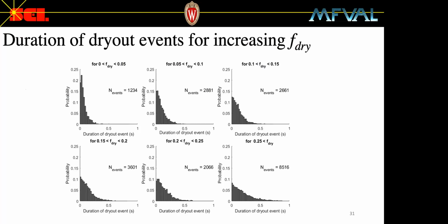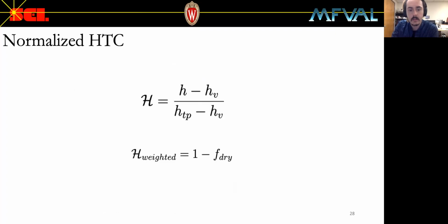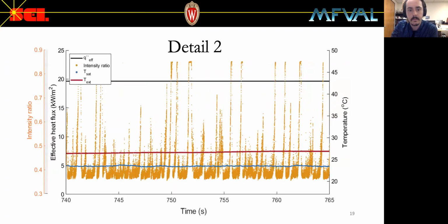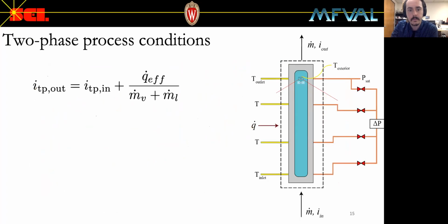It is, yeah. We actually do have small thermocouples. When I go back to the test section figure, if you look here, these four are thermocouples that go into the Altem. There's a slit in a plug, and the thermocouples are really fine wires that we lay in that slit, and we've verified that they accurately measure the saturation temperature. So there are thermocouples along the edge, but we don't want to put something on the glass that protrudes into the liquid film. We want the liquid film to be as stable as possible, not disrupted by anything in the apparatus.